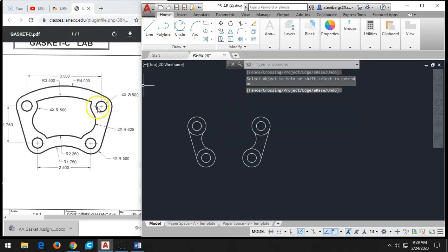All right, now I'm going to do the big arcs. So I'm going to do this big one on the outside and the big one on the outside here. And then instead of having to try and figure out where they touch in the middle of the objects, I'm just going to offset each of those up 0.5 or down 0.5 in this case, because I know that's the difference in radius between these two big arcs and between these two big arcs.